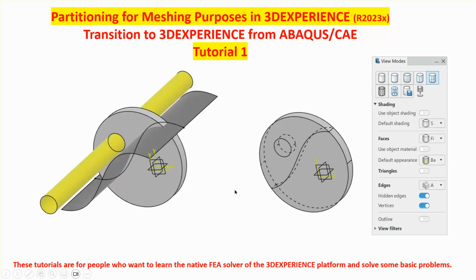So what we do here is we use these surfaces to create partitions, and that's different from really splitting. Partitions allow us to keep all the sides, and also when it comes to meshing, these can easily be done through hexahedral or brick element meshing, as you will see.